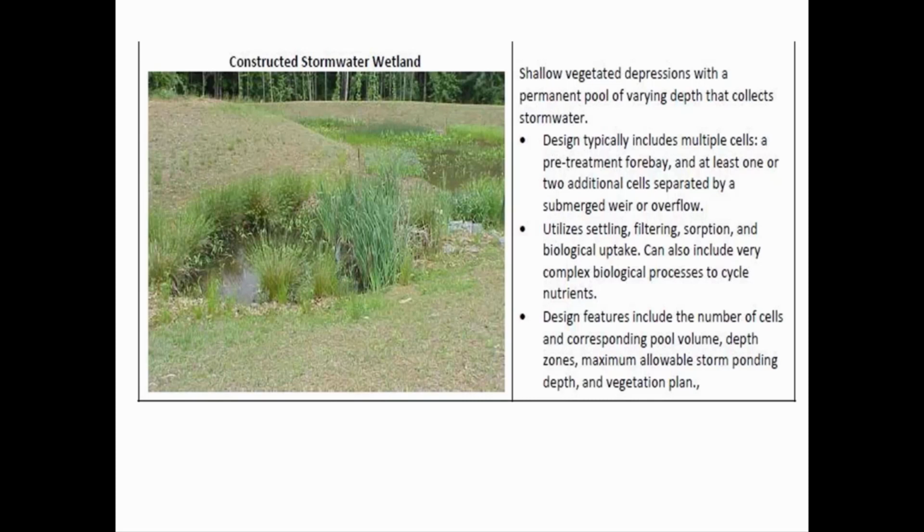And so there will be these what are called dead zones in the ocean where there's no dissolved oxygen, and it causes fish kill, and it can be pretty nasty, the breakdown of organic constituents in the absence of oxygen, the anaerobic consumption of organic material can form like hydrogen sulfide, which is corrosive, and we've talked about how it's dangerous for humans when it's in pipes and in an enclosed environment.